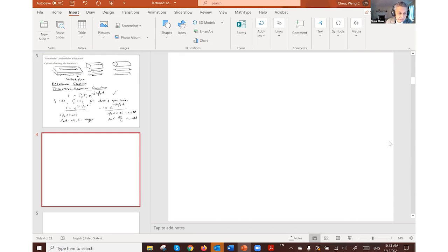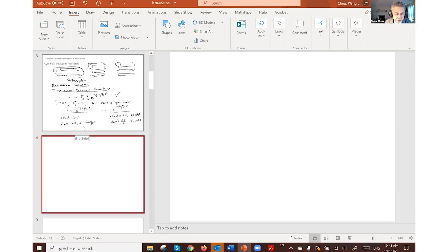And for the left-hand side one, which is the one shown here, the wave actually makes a full half wavelength from one end of the transmission line to the other end. So if I were to draw this transmission line, the left-hand solution will have solutions where it starts with 0 and it becomes something like that.